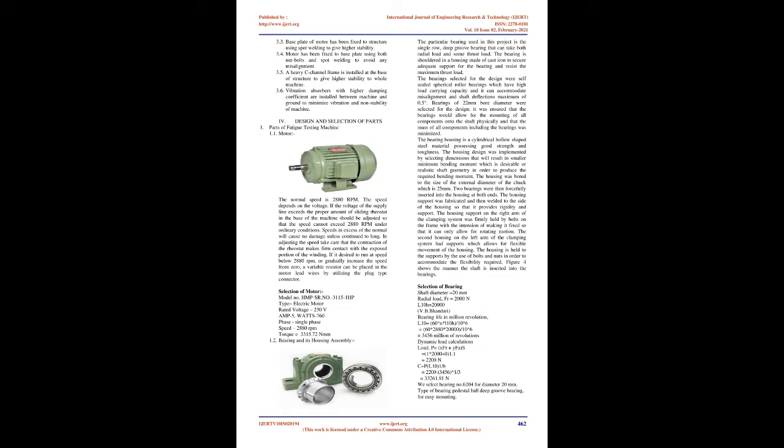Drawbacks of existing machine. Alignment issues. Eccentricity occurred in upper components as the drill chuck was fixed with both driving and driven pulley. Intense vibrations were produced during running of the machine due to this misalignment. The shaft gets buckled at the load points due to unnecessarily long length of driving and driven shaft. Base plates of the motor were partially bolted and partially welded, causing misalignment.